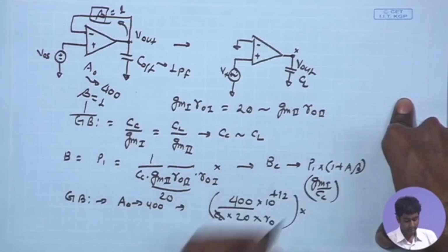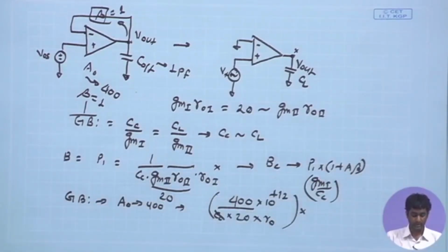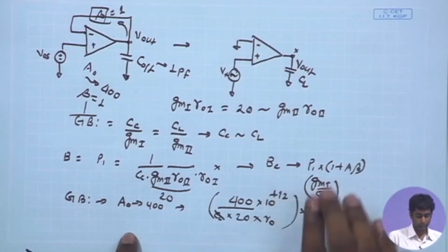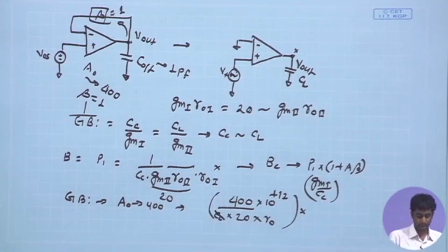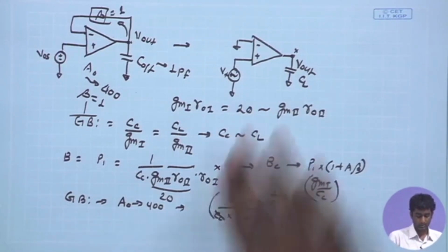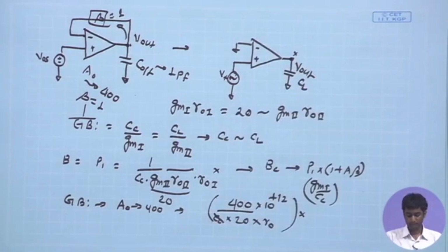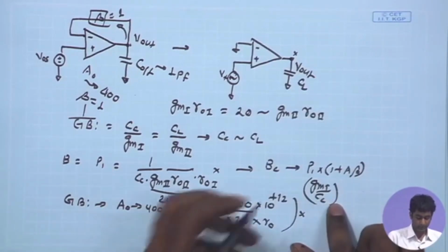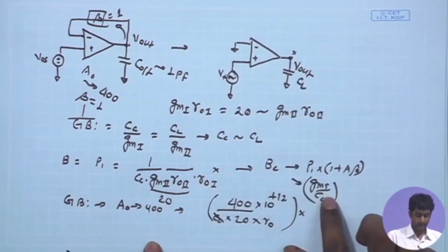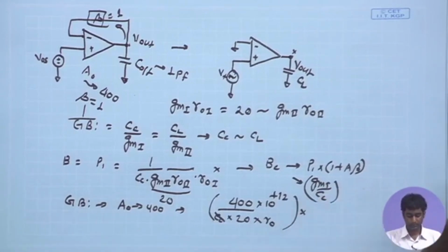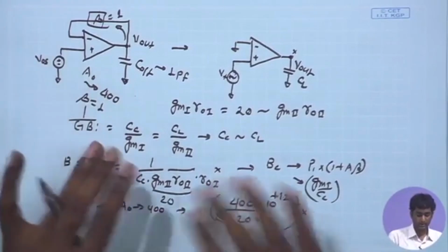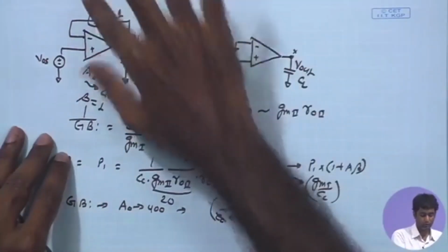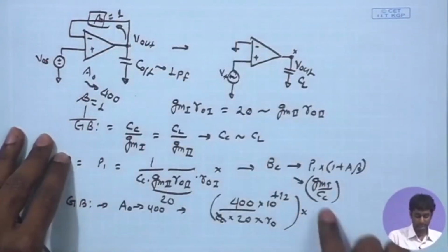This is nothing else but my gain bandwidth product. So, the closed loop bandwidth, in this case, is equal to the gain bandwidth product provided by the open loop amplifier, and I have to see whether this closed loop bandwidth is sufficient so that we can operate this closed loop operation fast enough by our clocking scheme.